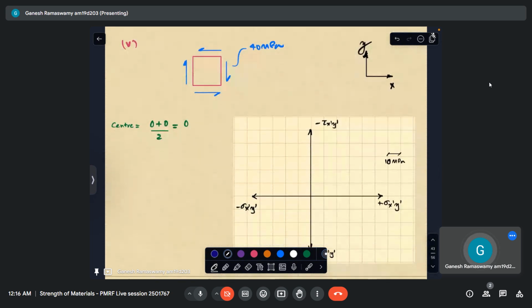Let us look at this where there is no normal stress essentially. So the center is at the origin. So we have the center at the origin and the x plane. The x plane has no normal stress. So the x axis will be 0. That is the horizontal value is 0. And as for the vertical value on the positive x plane, our shear points downward. So this is essentially negative shear.